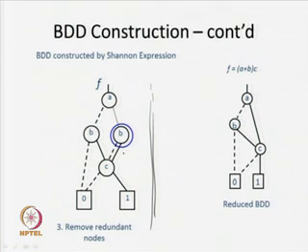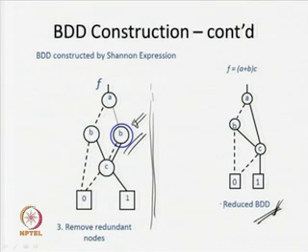So, when I come to this particular BDD, we have found that this particular node B is doing some sort of redundant test only, because B equal to 0 and 1 are going to have the same subfunction. So, we can remove this redundant node, and ultimately we are coming to this particular BDD. So, whatever you do, if we start from BDT, or you apply Shannon expansion to get your BDD, eventually we can apply those reduction rules, and finally we come to a particular BDD. Okay. So, we are coming to this particular BDD, and no more reduction is possible over here.